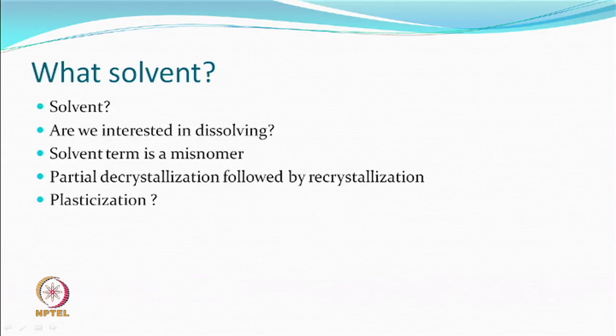The word solvent always means it will dissolve something, right, but we are not interested in dissolving the fiber. It is like we are not interested in melting the fiber in thermomechanical texturing. So, in some sense this term solvent is a misnomer. It is not dissolving the fiber. Actually, this term has come because various organic compounds are called solvents. They are solvents for something or the other, not necessarily for the fiber which we want to texturize.